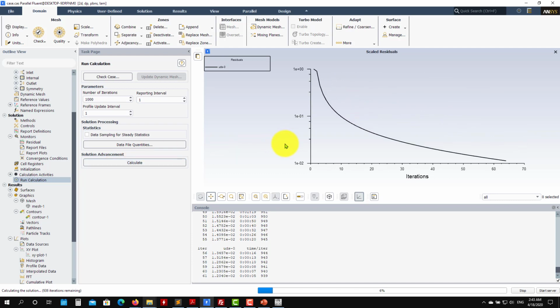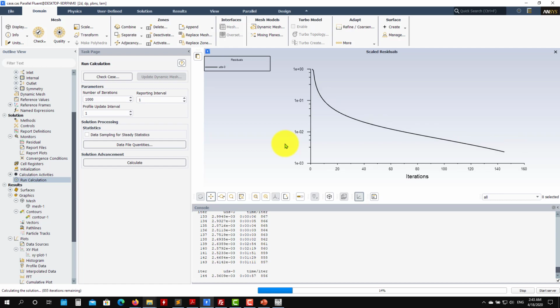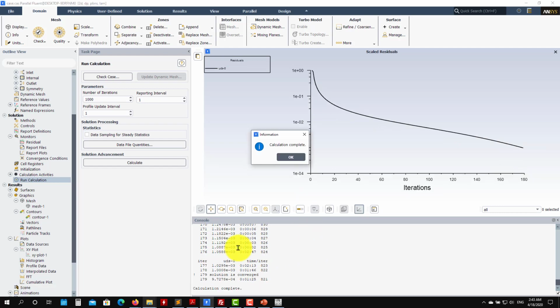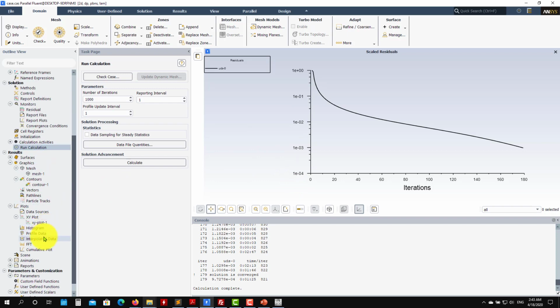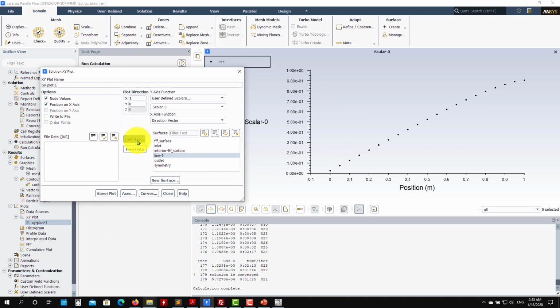So we iterate again, we start to iterate. See that it's a relatively easy problem, and we're only solving one equation here, but taking that many iterations is not good. And see that we load the file again. Now we have it shifted here. It's clear that we start to see numerical diffusion.